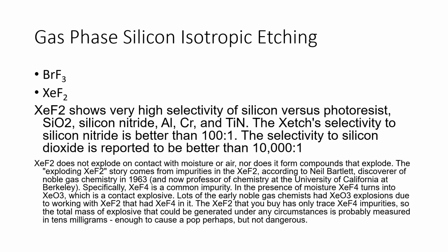The only thing that you have to be aware of is that you require a special etching chamber because the bromine trifluoride and xenon difluoride, when they react with any moisture in the air, would form highly concentrated hydrofluoric acid. So it is very important to be safe.